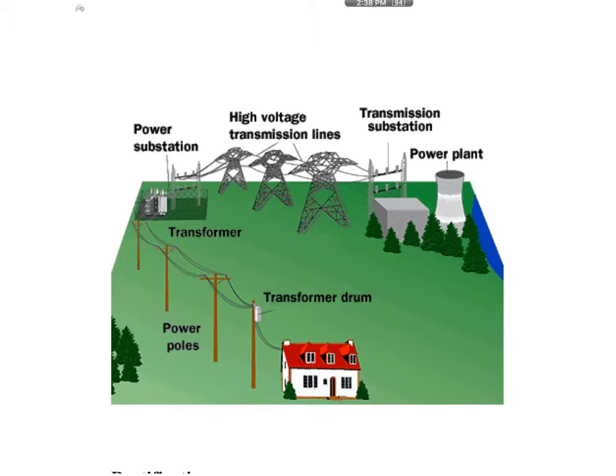How you turn the turbines depends. Some people will use fuel like diesel, or use coal, or use natural gas, and then they will burn it. So there are two ways. After you burn it, you can straight away use the exhaust gases to turn the turbine, but it is very inefficient because all the heat that you generated is just wasted, because you're just using the exhaust gases.